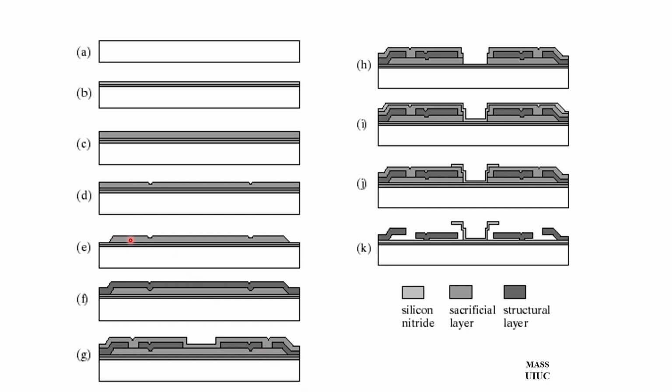Once you have a sacrificial layer with a dimple, then you can continue with the first layer of structural layers, second sacrificial layer, and the next structural layer serving as anchor, and so on. This process, compared to the previous one, obviously would take more time. The cycle time would be longer, the robustness would be lower, but it does result in a better, more robust process, and perhaps a better rotor.